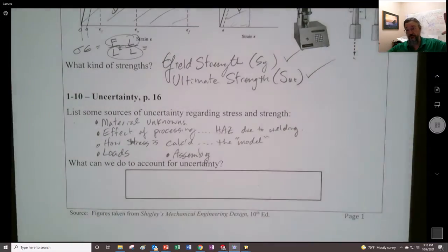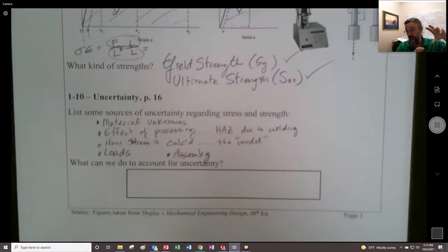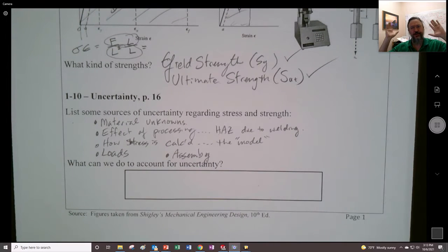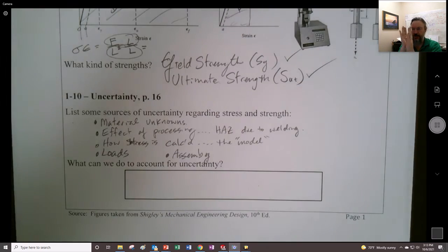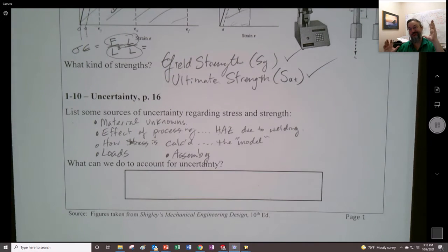We're talking big pipes with bolted flange joints, and inevitably you take something apart, you try to put it back together, and the center lines of the pipe are off, down and over to the side. Sometimes you even get one of those chain falls, which is like a pulley made of chains, and you put it up against the bulkhead, and you make these two things line up with each other, and you put bolts inside there.